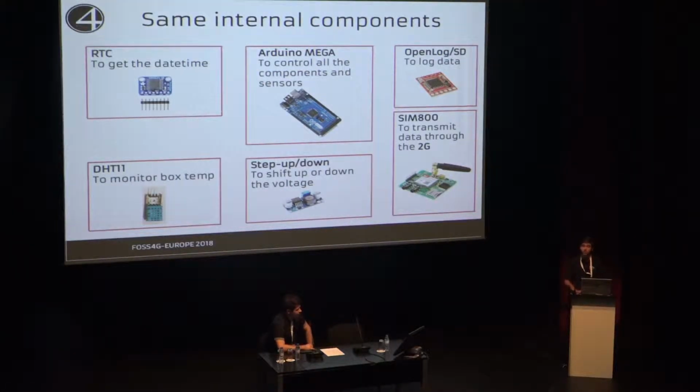These 2 solutions share the same internal components. So in the main box, we have the Arduino as main controller. We have the RTC to get the date and time, the OpenLog to store the data, to have a backup of the data that we are sending. And we are using the SIM800 to transmit the data, and then the DHT11 to monitor the internal temperature because we are deploying the system in Sri Lanka where there are high temperatures.